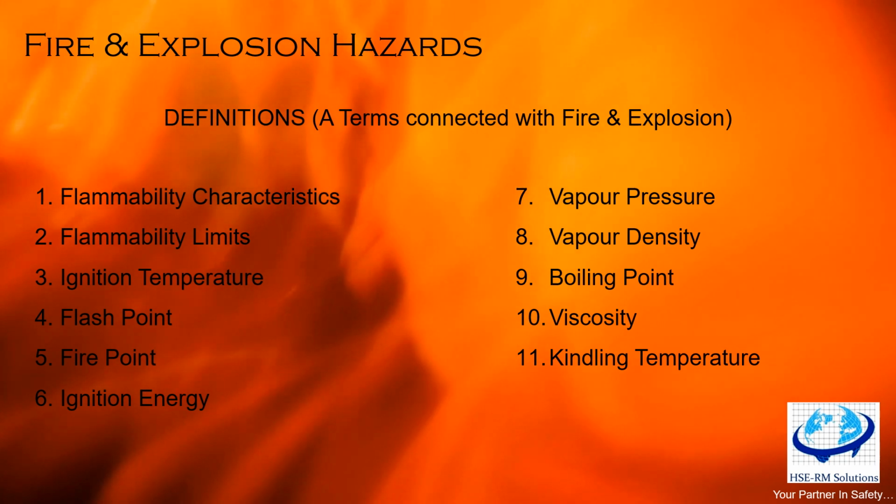However, viscous oil sprayed in a mist form with 10 micron size evaporates faster and behaves like a vapor. So if you have a viscous oil, like grease, and it is sprayed, it vaporizes faster, and when it vaporizes faster it is again more dangerous, because it will act similarly to its liquid counterpart.